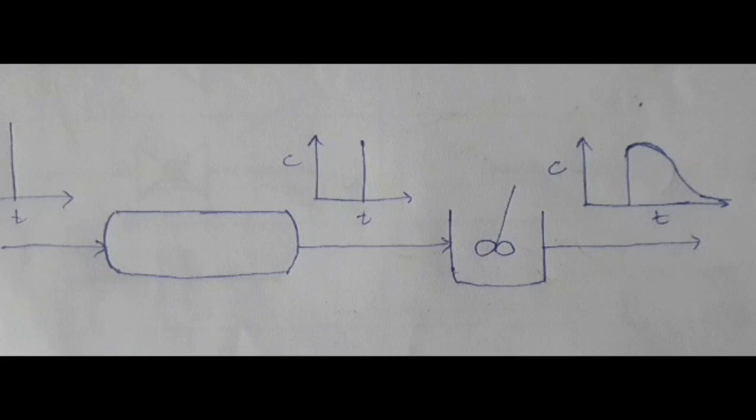If we compare the individual reactors, that is CFR and MFR, with the continuous combined flow reactor, we discuss the residence time distribution. As you can see from this figure, the residence time distribution increases as we go from CFR to MFR. This residence time distribution shows us that there has been proper mixing, and if we compare that to CFR and MFR individually at the same flow rate, then we might not find the same distribution.